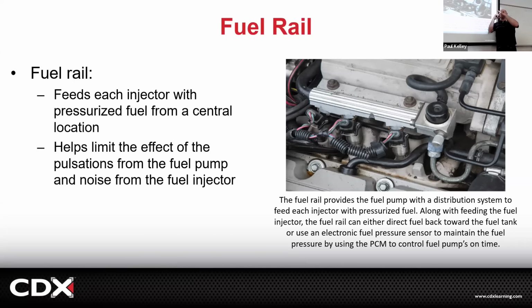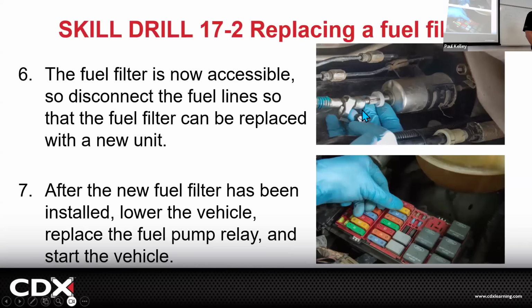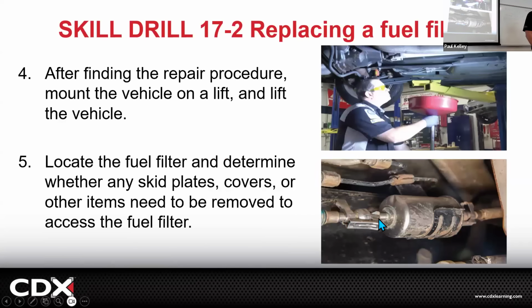If you're forcing it on, a lot of times the O-ring is starting to roll out of the groove. That's a scary thing. He did two things. He messed up an O-ring, but also where the fuel line was, back here, you notice there's this little clip that we pulled off right there. That's a safety clip to make sure it's clipped in all the way. He couldn't get it back on, so he threw it out.